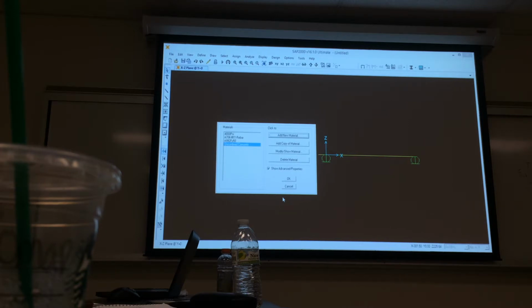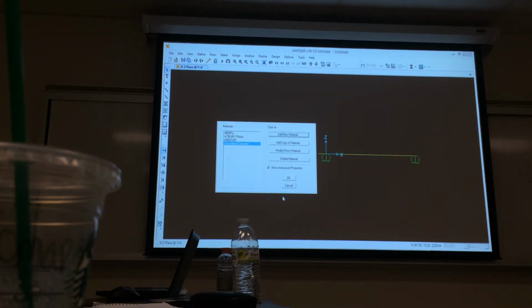And so realistically speaking, in most projects you do, you probably want to have, let's say, a suite of bar tests available to you of the steel that's going to be used in your cross section. So I say just use the standard nominal values, bump them up to these expected values, and go with that. But if you're doing a sufficiently large project, it may be of interest to make sure that you do lab tests of your materials. You may test 5 or 6 different rebar that are going to go into your cross section, and make sure you have the appropriate stress strain profiles for your longitudinal bars, your transverse bars, et cetera. It really depends on the project.